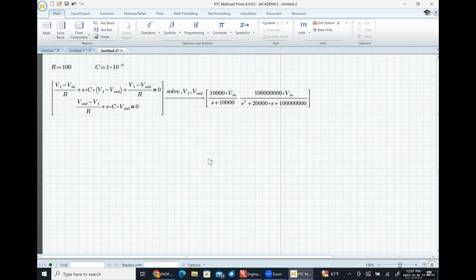So looking at this transfer function in the S domain lets us figure out what type of filter we have pretty easily. And it took a lot less work to get the same result that we would have gotten when we were looking at filters by looking at the transfer functions in the omega domain or the regular frequency domain, where we had to explicitly go back and find what the magnitude response looked like and the phase response. Right? So just a different way of looking at it with a little bit more context now. Okay. I think that's enough out of me for today.